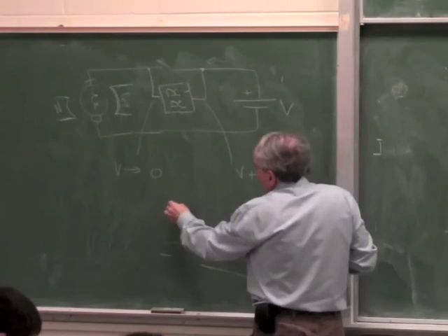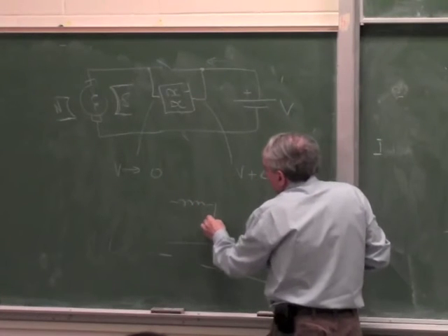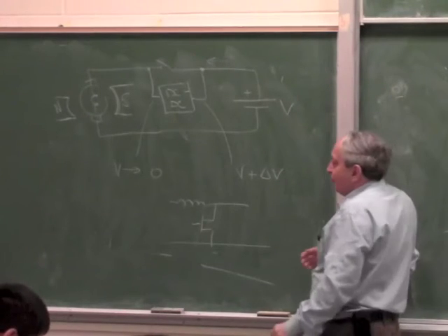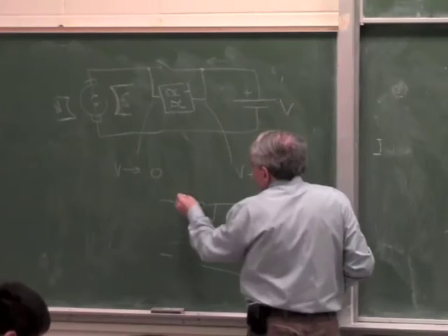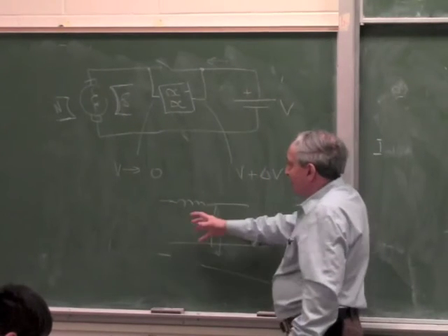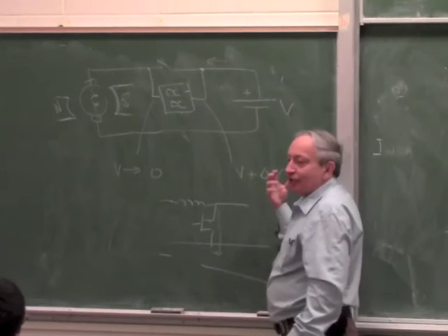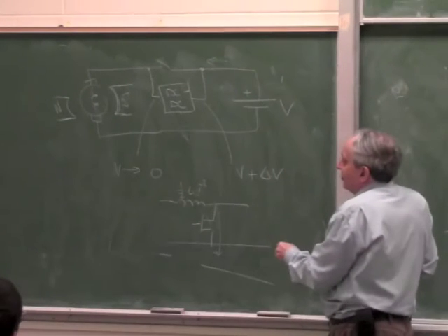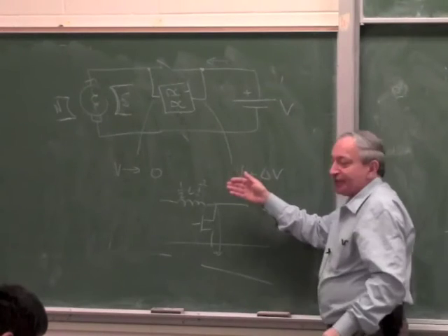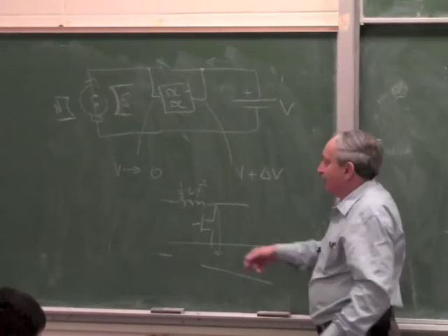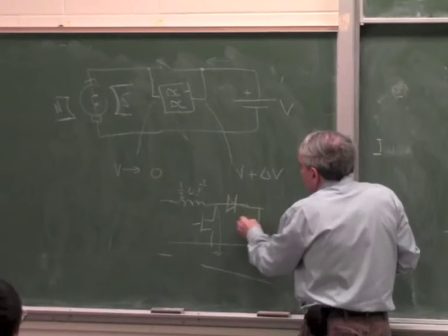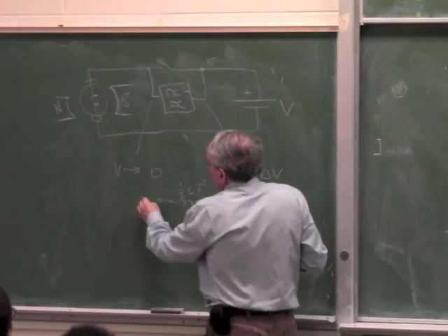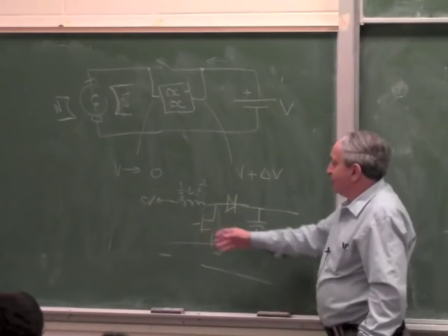Then if you take a coil and you run it through a switch, let's say a FET, okay? If you close this FET, the current will flow to ground. If you open this FET, the current wants to keep flowing because of stored energy, 1/2 Li squared. Because the current wants to keep flowing, the voltage here will become very high. It's trying to break down the switch. So now you can put a rectifier here and charge it up. So this way, even if this is, say, 5 volt, depending on how fast you open the switch, this could be 1000 volt.